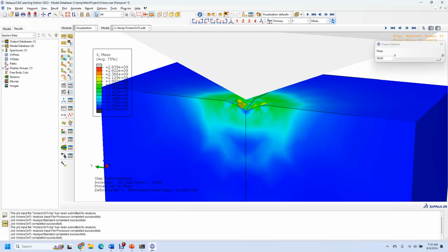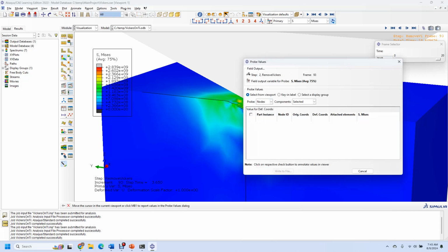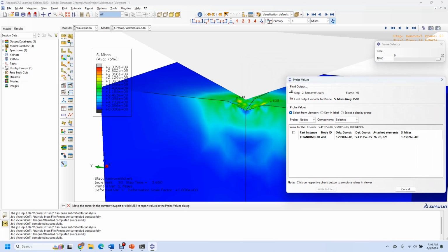So for calculating the hardness, what I did was I probed on these values, the furthest indentation point, and it's somewhere in here along that diagonal. And then I took these deformation coordinates, calculated the diagonal length from the origin, which is 0, 0.